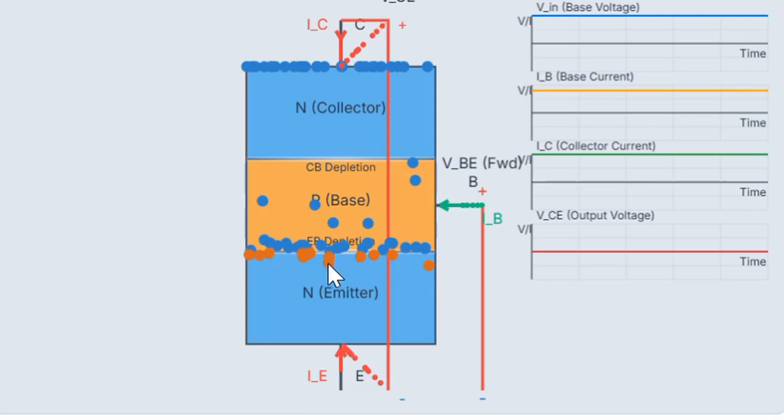The transistor acts like a closed switch, and a very small VCE is developed here. That means the VCE value drops to about 0.2 volts, depending on which type of semiconductor material is used. So you can see the graph, nothing has changed. The voltage is just 0.2 volt for silicon. In this region there is no depletion region, which means no electric field is present.